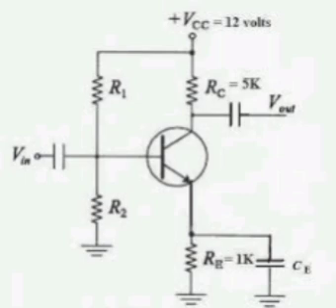If Vin greater than 0, VOA equal to negative, D1 off, D2 on. KCL: minus Vin minus 0 by R plus 0 minus 0 by R plus V0 minus 0 by R equal to 0. V0 equal to Vin. If VOA equal to positive, that implies D1 on, D2 off. Like that we have to calculate. Again, if we apply KCL: minus Vin minus 0 by R plus minus Vin minus 0 by R plus V0 minus 0 by R equal to 0. V0 equal to 2 times that of Vin.